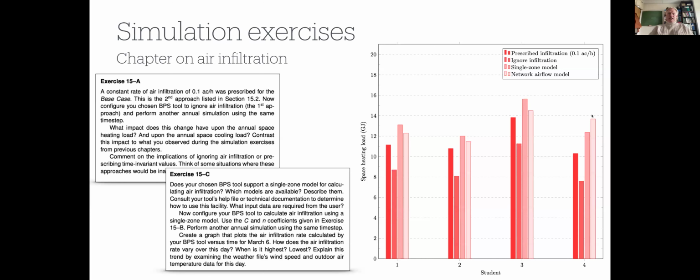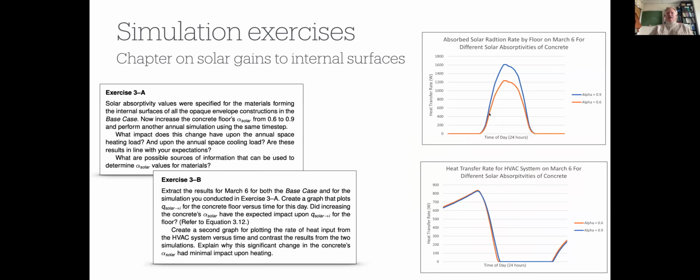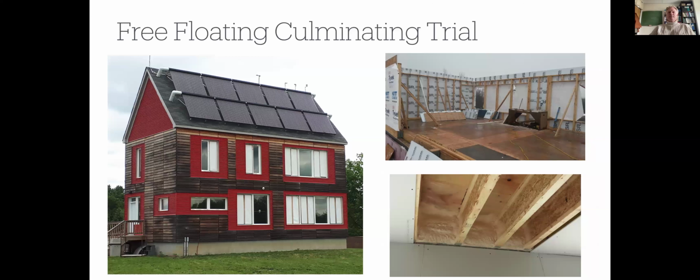And the takeaway from this is that treating air infiltration has much more of an impact on a result we're interested in, a space heating load, than defining the solar absorptivity of building materials. And that's a result that I want students to retain for future reference. So when they're faced with simulating the performance of an actual building, they realize where they should be placing their priorities, where they should be investing that precious time resource.